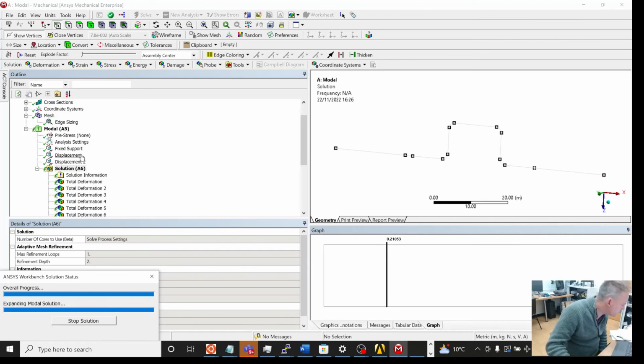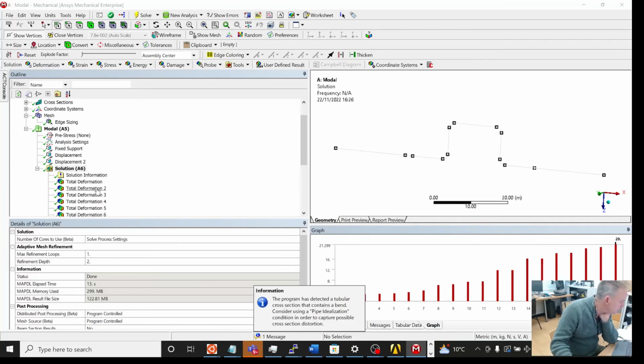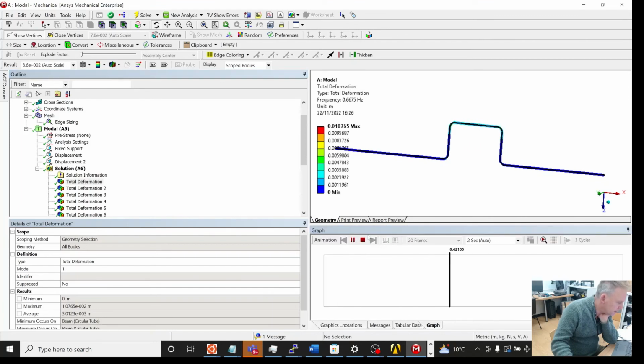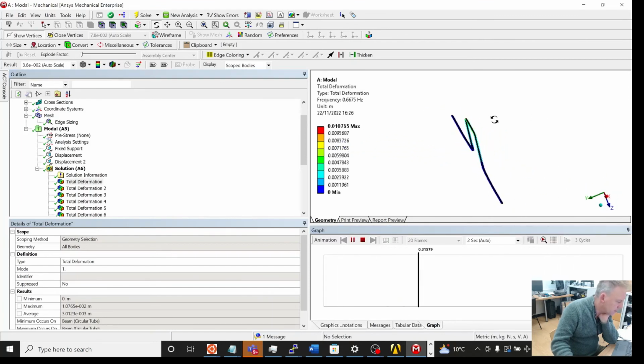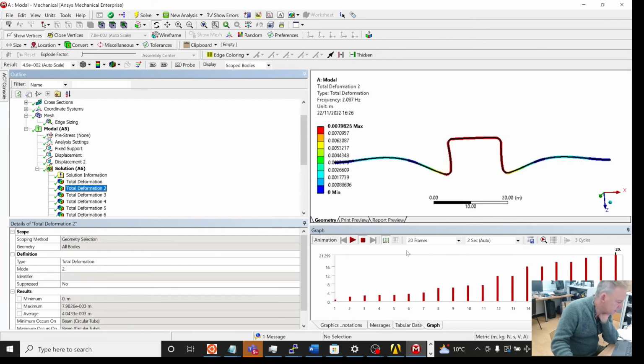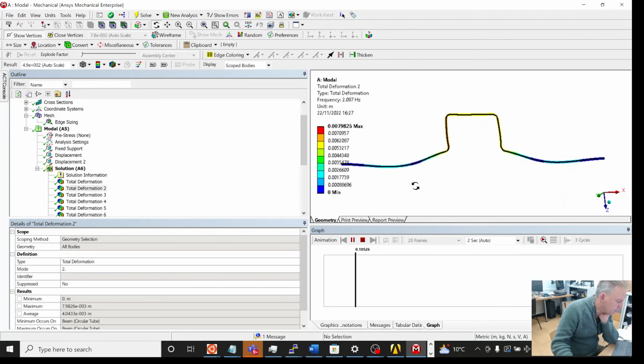When you do the displacements on fixed boundary conditions, I wouldn't try to group them together, I would do them one at a time, because I always get kind of lost. It's not very good at flagging up whether there are multiple boundary conditions applied. So let's go to the 0 displacement, the lowest mode, and look at that. Now it's a bit more sensible, backwards and forwards movement. Look at the second mode, you start to see other modes creeping in. Remember, the displacement in the center that we have here is fixed, and so it doesn't preclude the thing vibrating up and down.